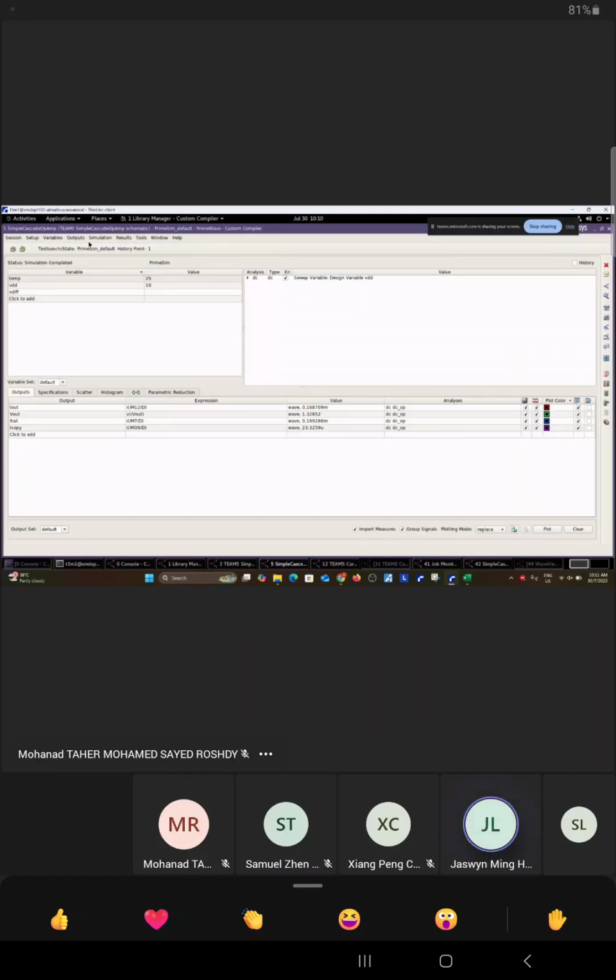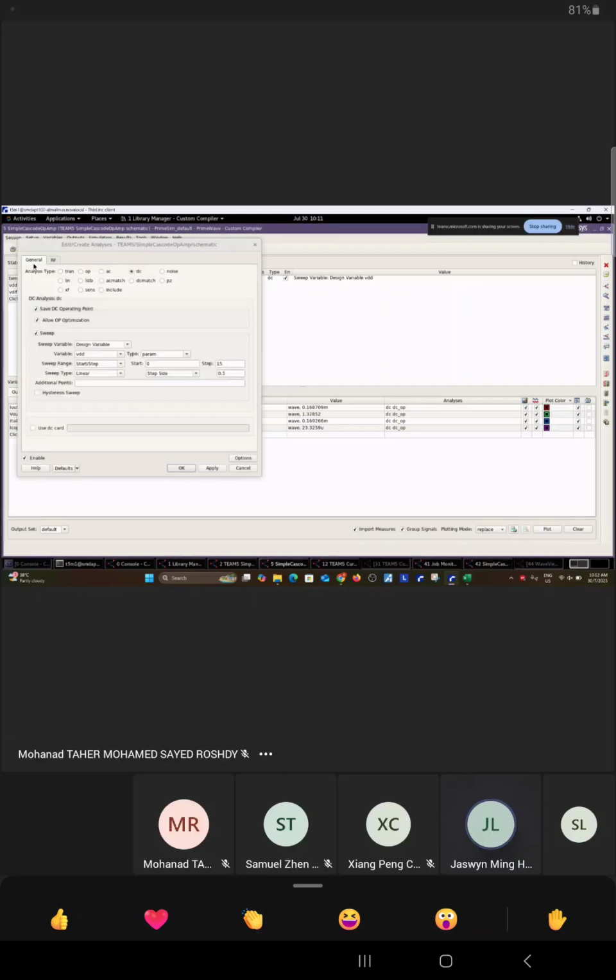Yeah, you only have 2, since you already hard coded the rest of the weights, there's no need to. So VDIF, we just give it what value first? VD we are going to sweep it. So we put -5 first, then later on we will initiate a sweep here. So set up analysis, DC. You put DC sweep, VDIF, from -5 to stop at 5. Then the step size, you can just maintain at 0.5. I think it's good enough.